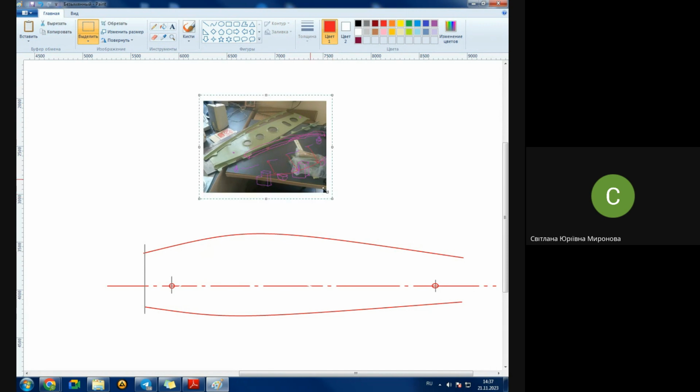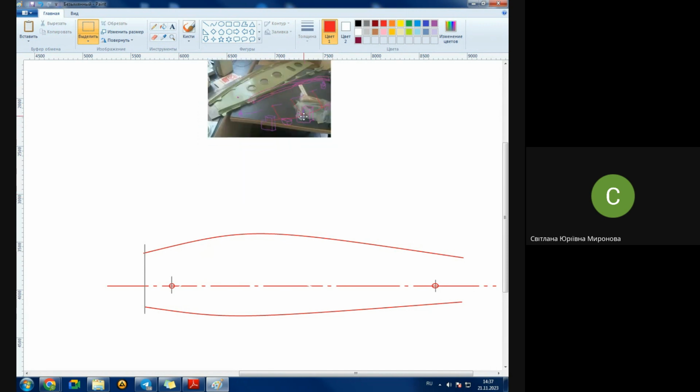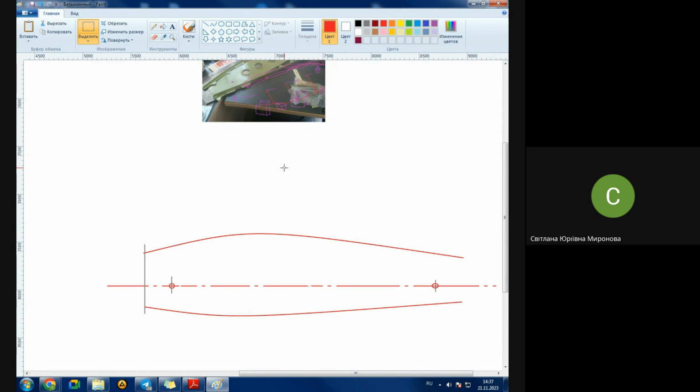To be frank, you may also go to the 3D models if you like, not compulsory like this. First, let's imagine that we are starting from the base axis. Next, we are drawing actually the structure of the rib or structure of the unit, but it's supposed to be given in so-called thin lines or double dot lines, not in solid lines.